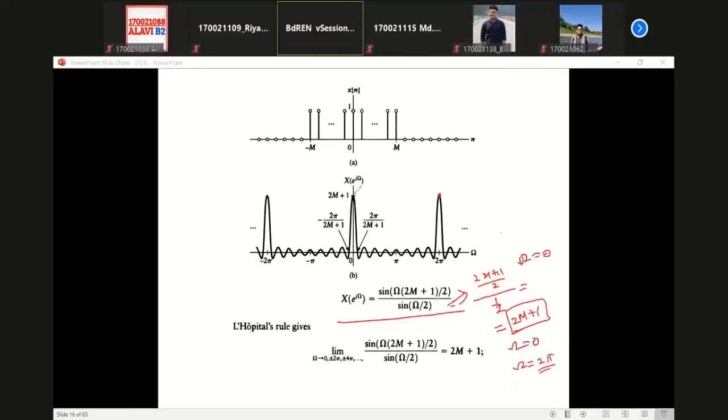So this is where the maximum values appear, okay? Then from minus pi to pi, it will constitute a cycle in your Fourier transform. From this, what you can understand is that at the receiving end, after processing, if we know the Fourier transform values from minus pi by 2 to pi by 2, we can reconstruct the signal. But you see that this 0 is occurring at this point, okay?